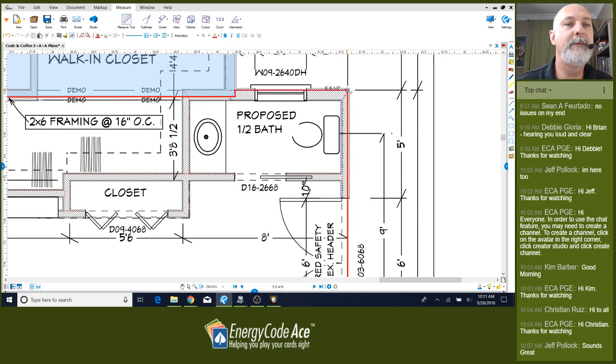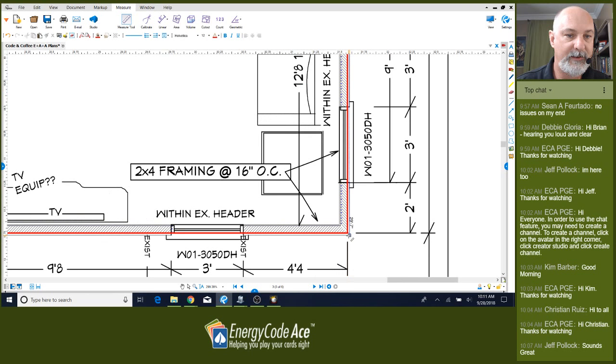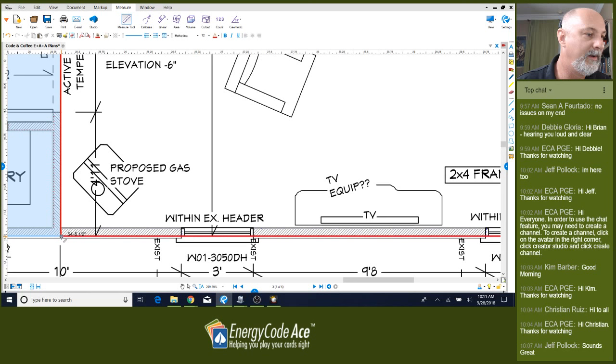Good. I'm using the perimeter dimension tool, just following around the outside here. When you use Bluebeam or other software, it may not be as choppy as this. I've got a lot of stuff running on my system right now. So we have 54.5 lineal feet of slab edge. All right, good. We've got our area takeoffs and a good idea.